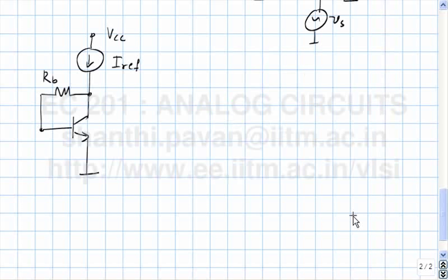In an NMOS transistor, the drain can go one threshold below the gate. In an NPN bipolar transistor, the lowest the collector can go is the base voltage itself. Okay, so now based on this new observation, can you comment on the usefulness of this bias technique? Assume that the base current is very small.